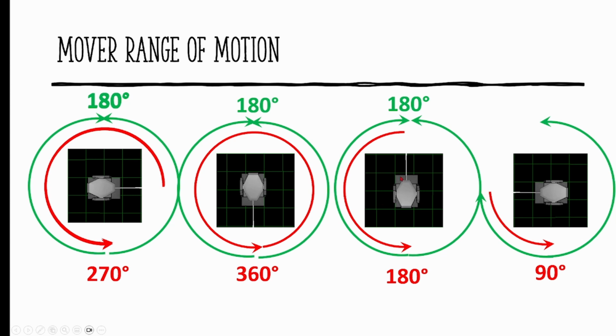Now, the one position that you don't want or can't mount it in is pointing to the left. And this is for counterclockwise only. If you have a clockwise rotating moving head, all of this is opposite. Okay? So with that being said, let's say you're moving heads here. Well, if I want to point to the front of the audience, if I only moved it 90 degrees, right?